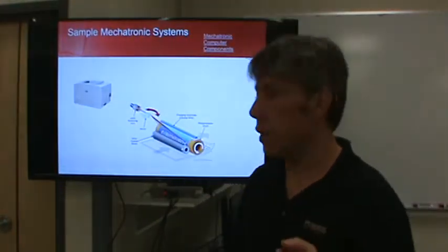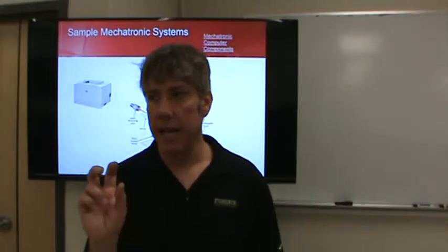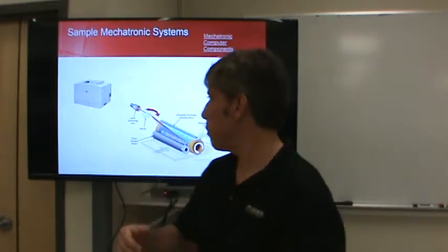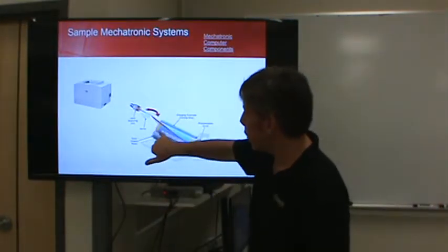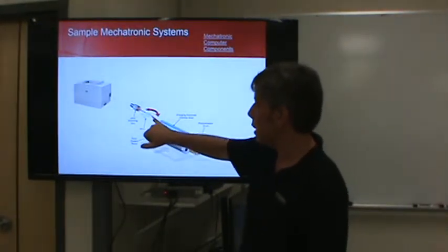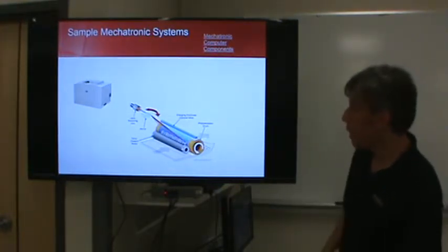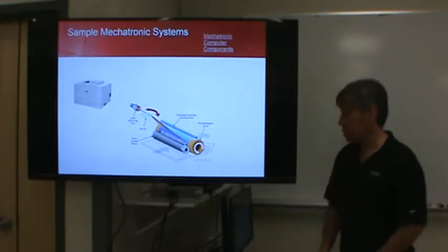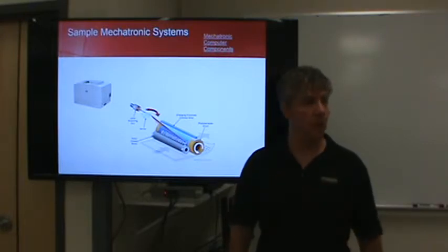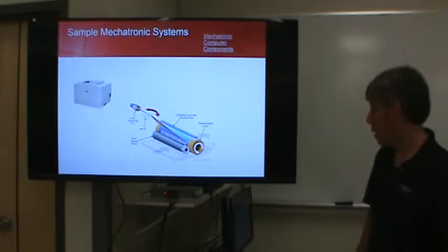What's interesting about that, you'll notice there's a chip on it, and that chip is a motion control chip. So what it's doing is keeping track of exactly where that motor is, and so exactly what the angle of the mirror is, so that you know exactly where on the page the beam is located. Okay? And the idea is that that laser is pulsed in order to create the image on the photoreceptor drum. So it's really interesting, because if you want precise text and things, you have to know exactly where that laser beam is. And so that's a mechatronic system. It's a computer-controlled precision mechanical system.